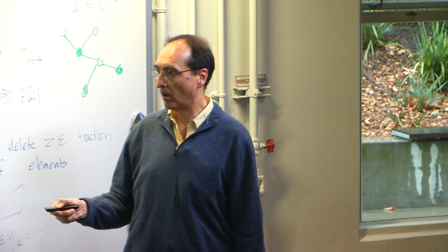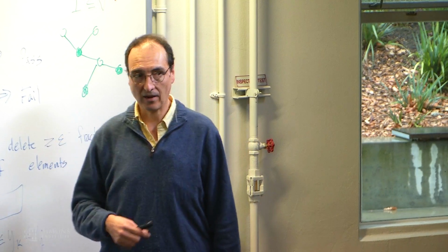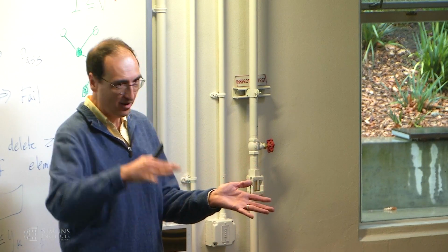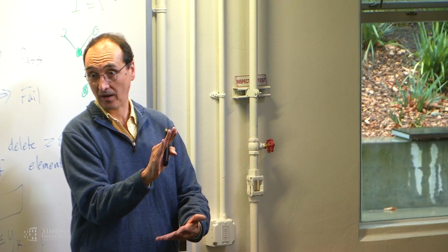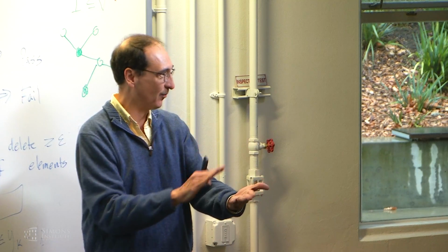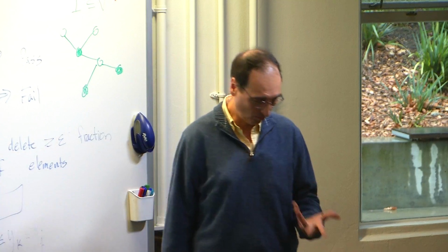I probably also want the disturbances to be attenuated. Remember in my cruise control example, this was the hill. I want the effect of the hill to be small. If I didn't have this controller in there, I would just hold the gas at some level, and when I went up the hill, I'd slow down. So I've got some effect, and I'd like less effect than that. Instead of slowing down 10 miles an hour when I go up the hill, I slow down 0.1 miles an hour or something like that. So we can write those things down.